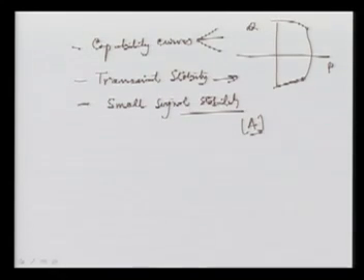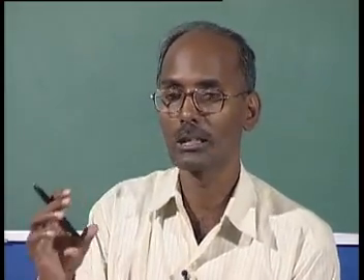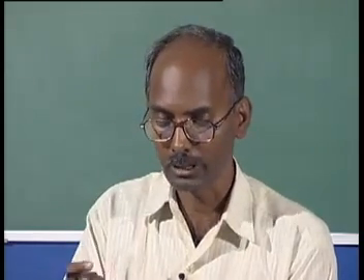We use eigenvectors, eigenvalues, and the participation factors to do this, and small signal stability is especially related with small oscillations in the power system. So how can we improve it? Already we discussed some modal analysis. We also saw some improvement methods for small signal stability as well.